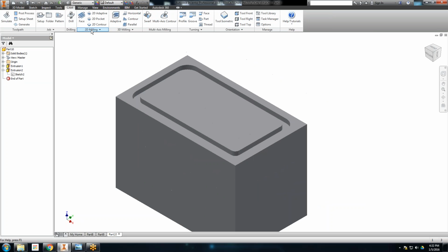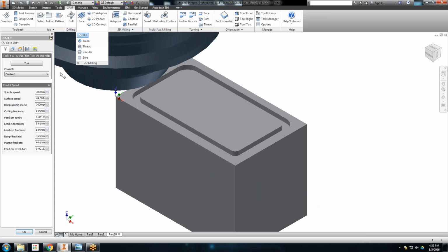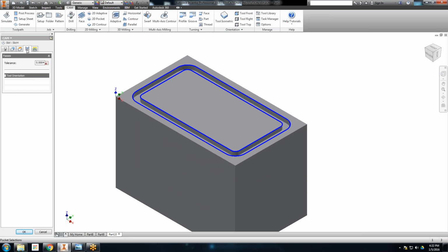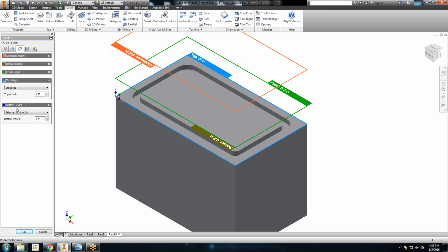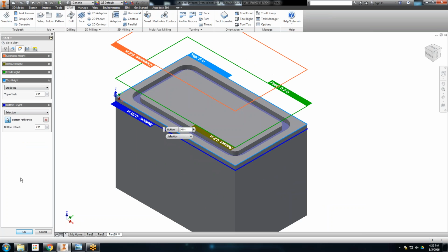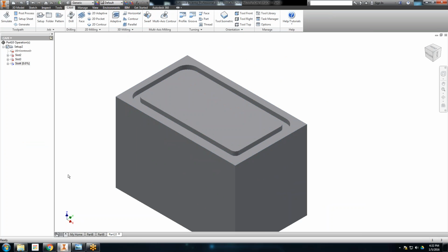So that shouldn't give me any problem, although since it's a Tuesday, it'll probably give me problems. But if I just went into sketch mode and did the offset command, would that create that same thing, or is that not what offset does? Offset will ruin it; it won't keep the radius the same. It'll offset, but it'll change the radius in the corner when you use the offset command.